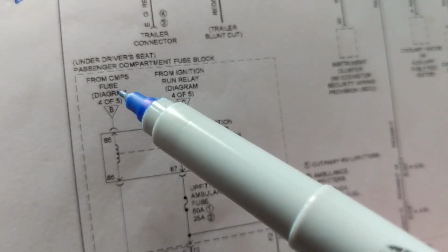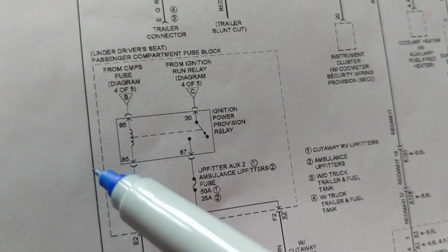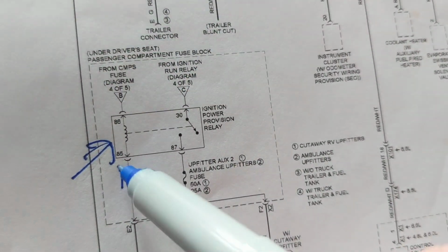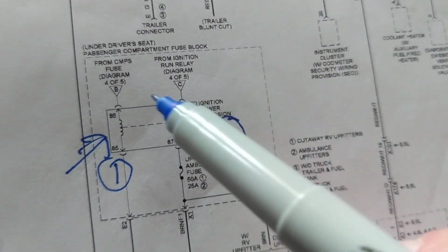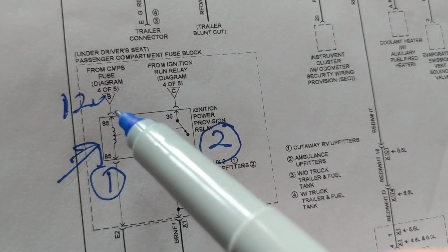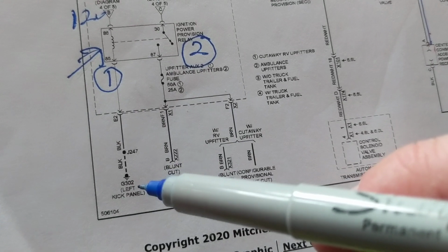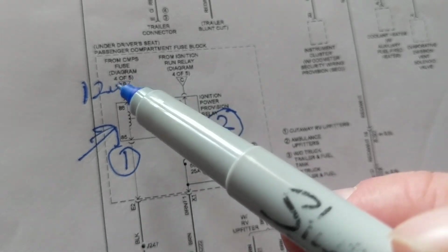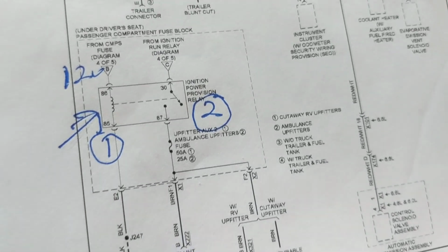So therefore, we need two things first to operate. The first thing of a relay is we need this part of the circuit to be activated. This is number one priority, number one. When this happens, number two can take place. There's 12 volts here. Sometimes 12 volts can come right from a fuse, sometimes from the ignition switch, sometimes from a computer. If we have the ground, that means the 12 volts is coming from somewhere else. If we have the 12 volts but we don't have a ground, the ground can be coming from a computer, giving it a ground.